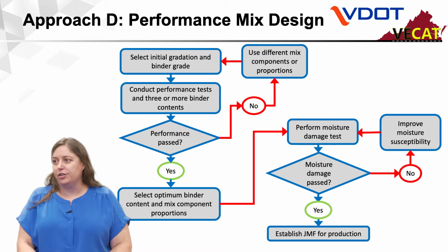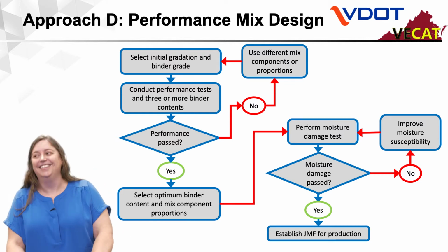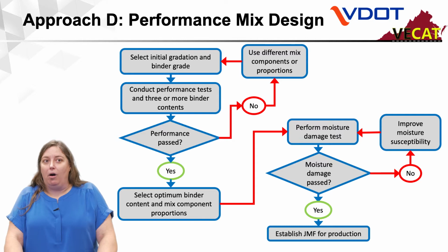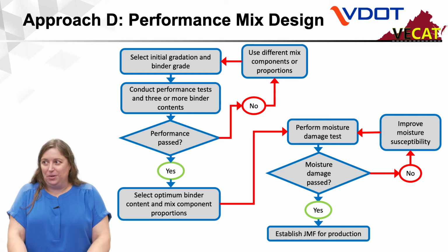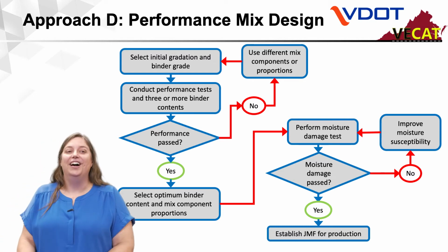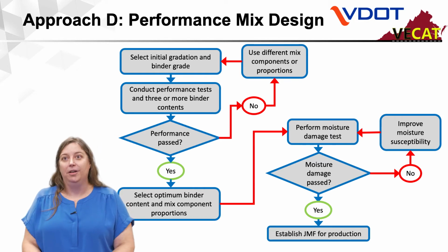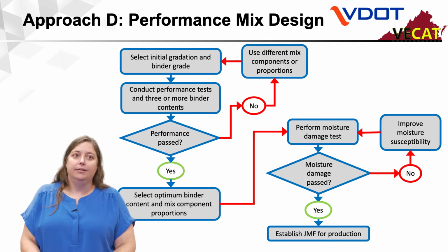That means no consideration of air voids, no consideration, technically speaking, of our VMA. All the constraints are off. However, as we all know, you can't go too wild. If your volumetrics are not going to be reasonable and rational, performance will never happen. So you still need to be aware of that.